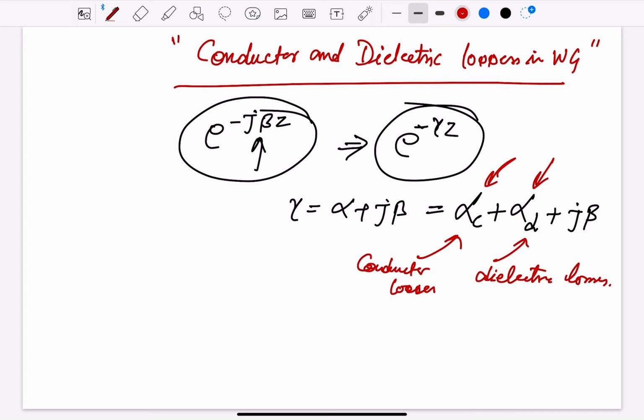As the name suggests, if you are making some changes in the fields for a particular mode, that has to be recorded. Since we know different modes, TE mode and TM mode, have different field distributions, and there are other variations too, we can say that each mode will have a different attenuation constant due to conductor losses.